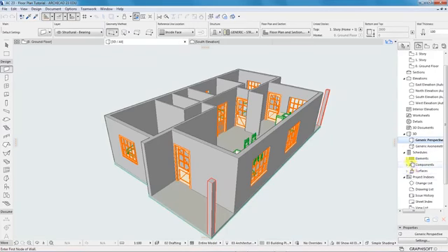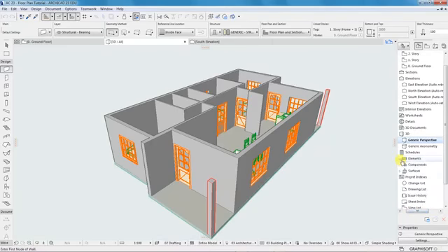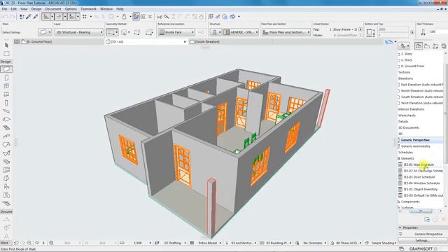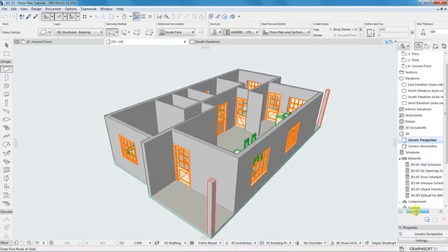Now to be able to see what types of elements we have, you'll click on the drop down for the elements, and you'll see that we have walls, which is represented in the wall schedule. We have all openings of doors, we have windows, objects, and default beam components. Now for us, we want to extract the quantity of materials that will be required to build the wall for this project. So what I will do is, under schedules, I will activate the wall schedule by double clicking on it.